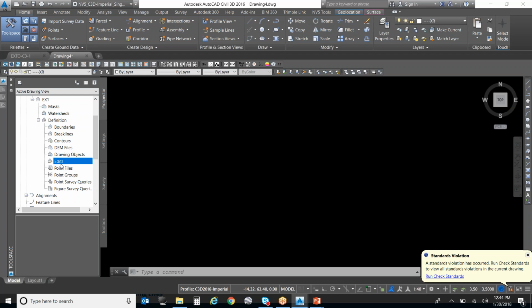Paint marks are actually very useful to use. I would actually recommend using paint marks on your initial surface because those are pretty accurate, right? They're usually found on pavement, which is a pretty easy surface to survey. So I would actually say include paint marks. The only thing about that is sometimes they're getting it in traffic areas and they're shooting it quickly so they don't get killed. So the accuracy isn't always that good.